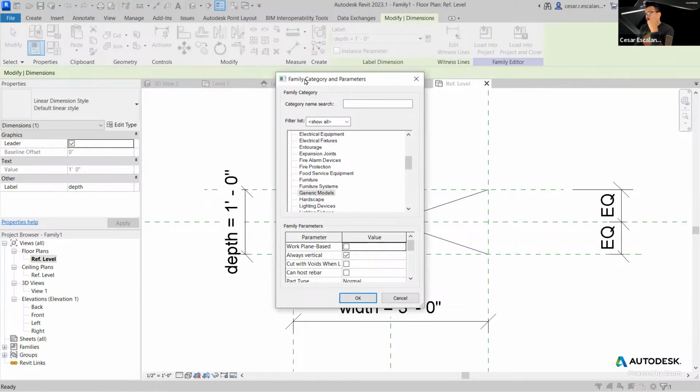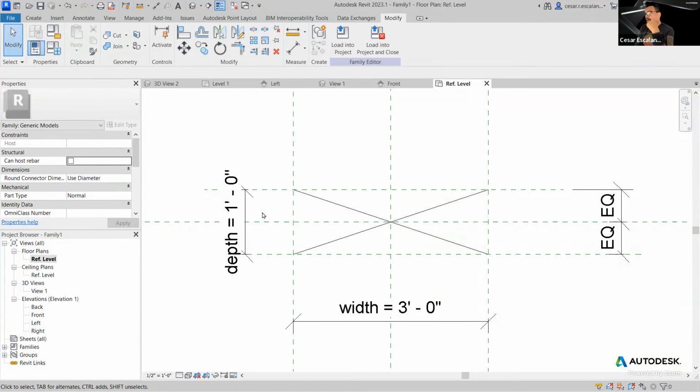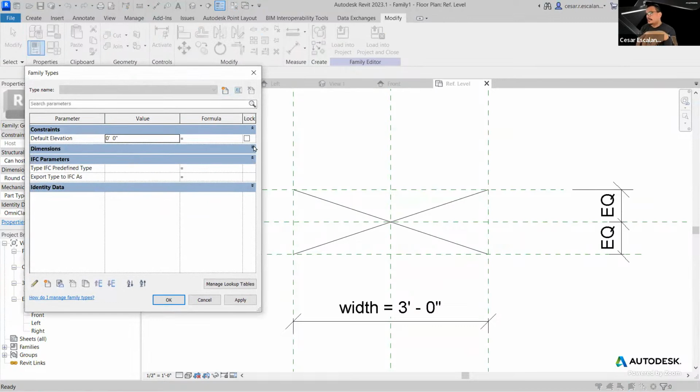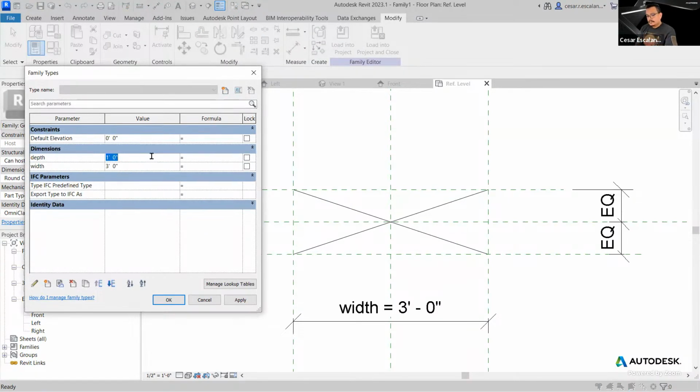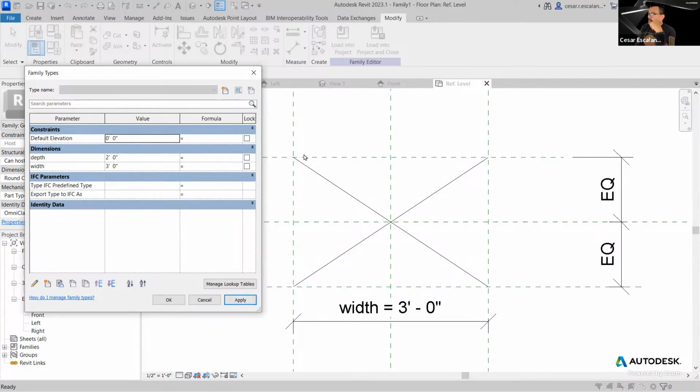All right, the other thing I wanna show you guys is that when you snap to the reference planes, you don't need to establish align locks. So notice how I'm gonna try to flex this. And notice how this diagonal, because it's snapping to the intersection of 2 reference planes, then it established an automatic lock. And this is a property of snapping to reference planes. There's no need to lock it. Revit creates this automatic relationship with intersection of reference planes.